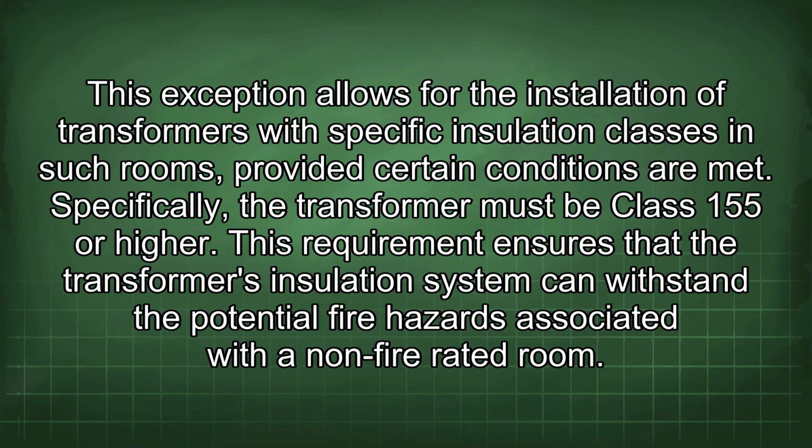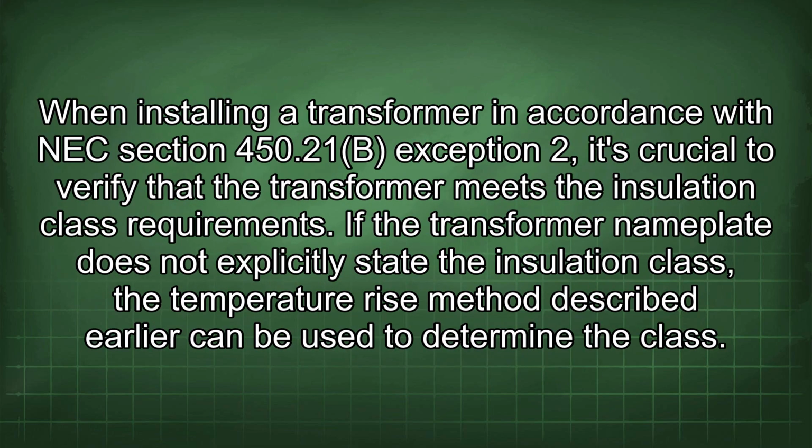Specifically, the transformer must be Class 155 or higher. This requirement ensures that the transformer's insulation system can withstand the potential fire hazards associated with the non-fire rated room. When installing a transformer in accordance with NEC Section 450.21(B) Exception 2, it's crucial to verify that the transformer meets the insulation class requirements.